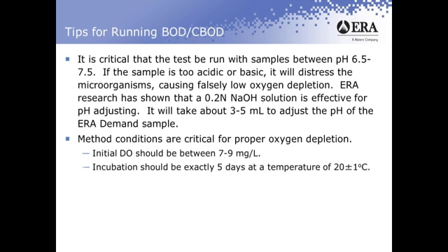Your incubation period is 5 days, and you want to make sure that you're incubating your sample for the exact amount of time in the method, and that your temperature is 20 degrees plus or minus 1 degree C. The reasoning for that is if your temperature is too high, it speeds up the microorganisms and you'll get too much oxygen depletion. If your temperature is too low, it slows down the microorganisms and you'll get too little oxygen depletion. For the method, your dissolved oxygen or DO difference should be at least 2 milligrams per liter, and you should have at least 1 milligram per liter of residual DO.